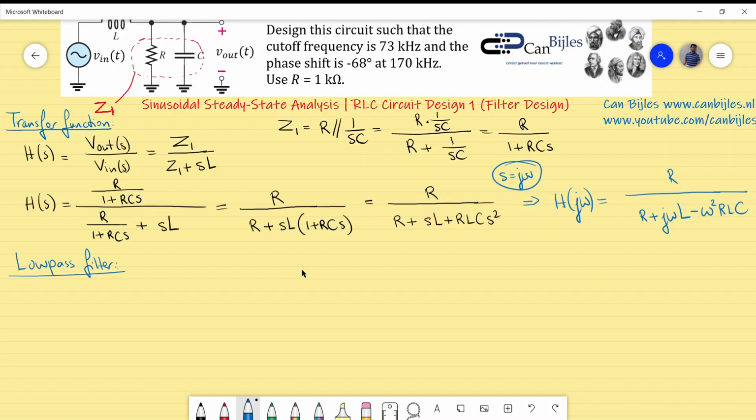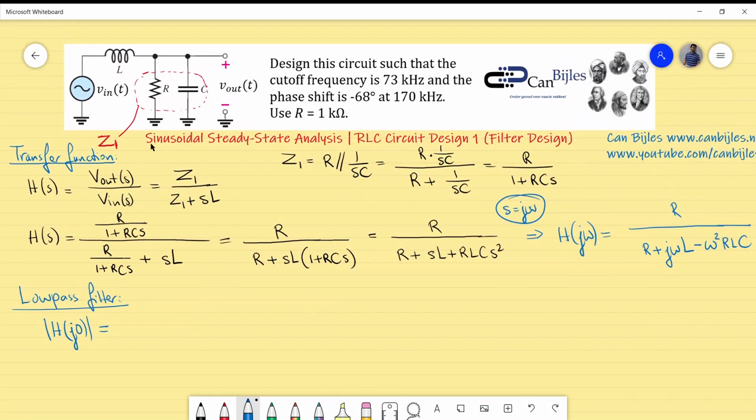Okay, that will mean actually the following: your low pass filter, because it's a transfer function H, will have at DC a specific value. But what is the specific value of your low pass filter for this part? So if I look at it again, for DC this will be a short, this will be an open, and the voltage here will be supplied in total to this node. So actually I have a transfer of 1.